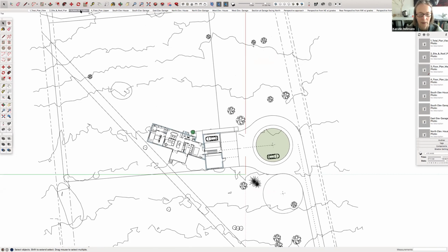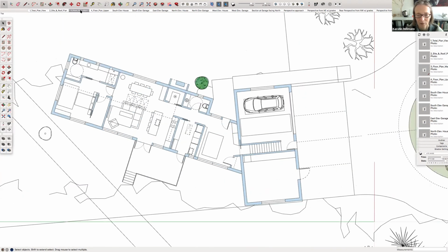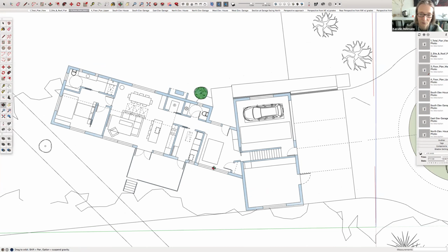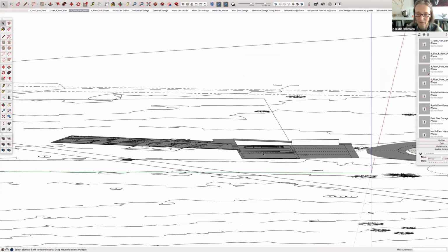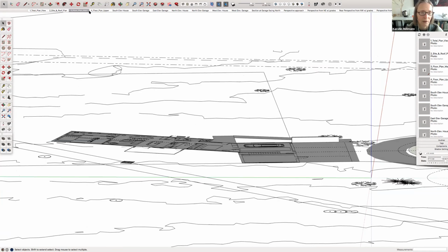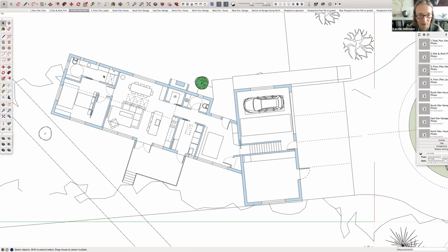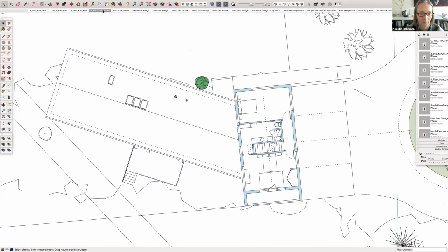And now I did something because I've kind of learned from having to redo my model every time they made changes. I actually have the floor plans as 2D layers in there. This is just my 2 floor plans at different heights in the bottom of the model, and the model is turned off for this particular view. This way I can make changes more quickly without having to remodel the whole interior. And then this is the upper level floor plan.